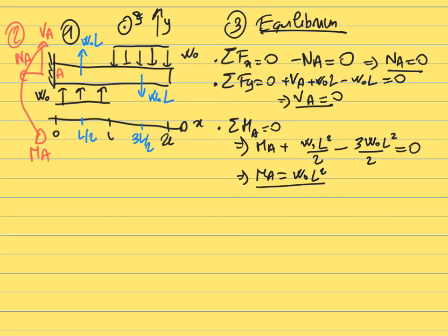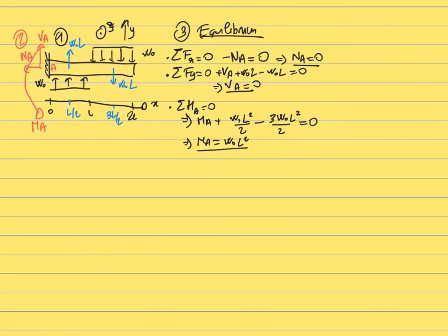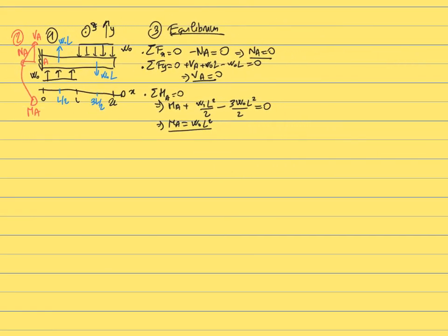So that was step 3. In this kind of bending problem, despite the fact that we are using a graphical method, we always need to first calculate the equilibrium condition to find the value of the unknowns, which is what is going to give us the limit condition. So let's move this a little bit on the side, and let's go to the next step.